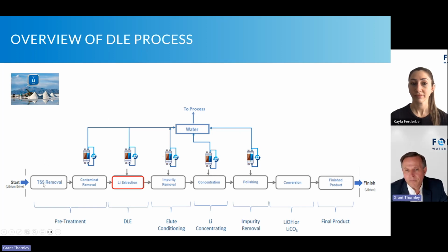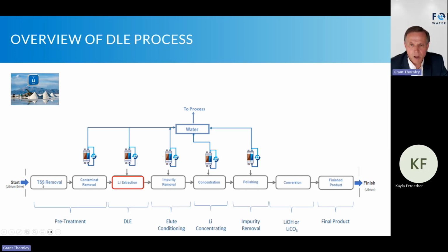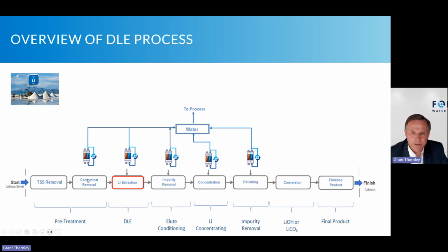If I take a look at block unit processes, a block diagram, I have a pre-DLE, which is any suspended solids removal, maybe some contaminant removal, maybe temperature or pH adjustment, and then into our lithium extraction. This is what we'll be talking about today, using LADH as our media for lithium extraction.